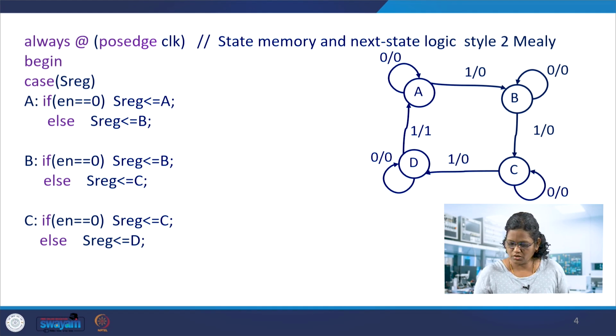We are just combining the state memory and the next state logic in this always block, and the output logic will be a separate always block.